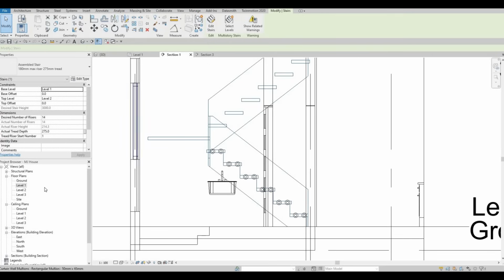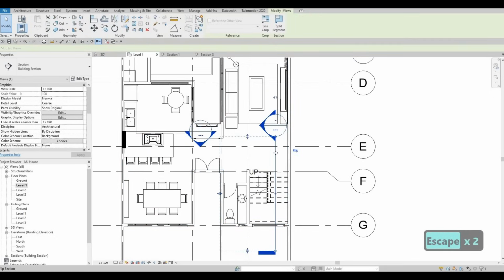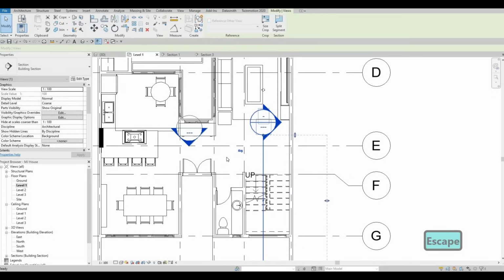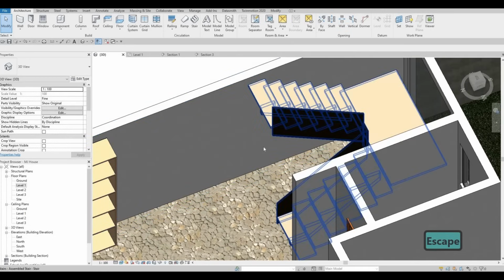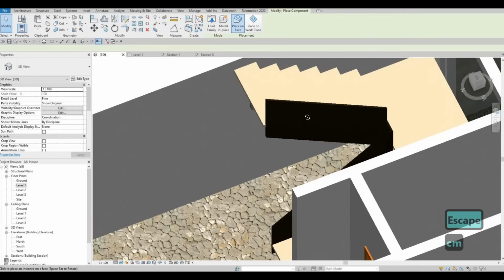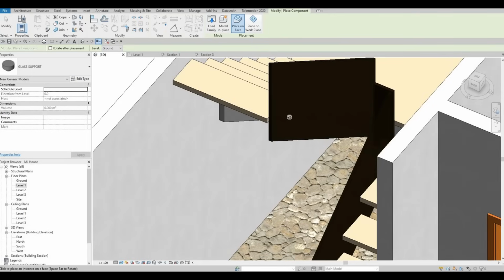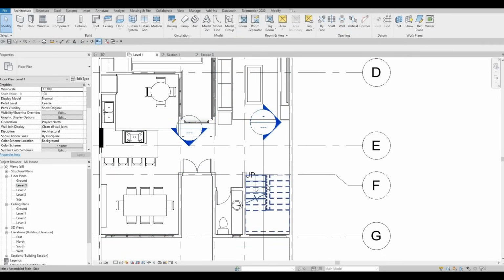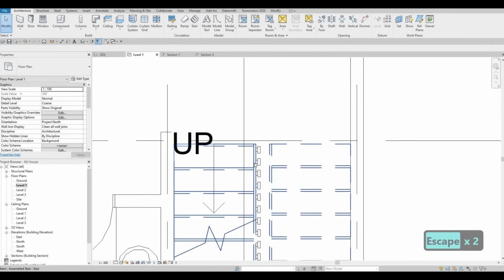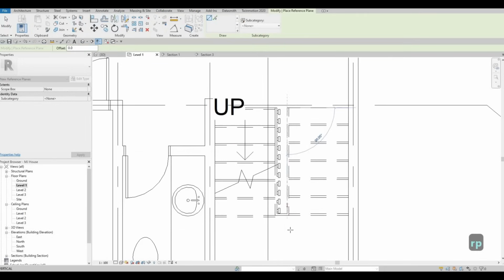And then now what I'm gonna do is I'm just gonna flip it on the other side, because we have it right there now. And let's go to 3D. Usually I place 1 cm on this, but for some reason it's not getting attached. So another solution, if you have the same issue, is to create a reference plane. So let's create a reference plane, RP. So reference plane right there.